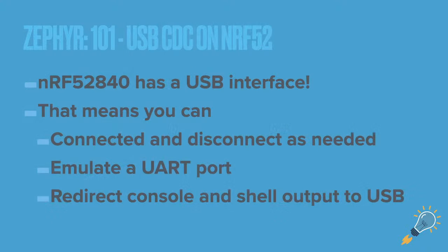So yeah, the nRF52840 has a USB interface. That means you can connect and disconnect as needed, and emulate the UART port, which is what we're focusing on here. The other thing you can do is redirect the console and the shell to the USB. That's particularly great because you don't need another UART interface to do that. You can use USB.